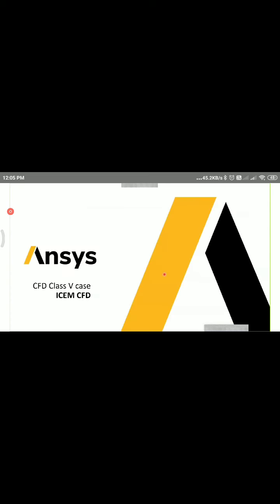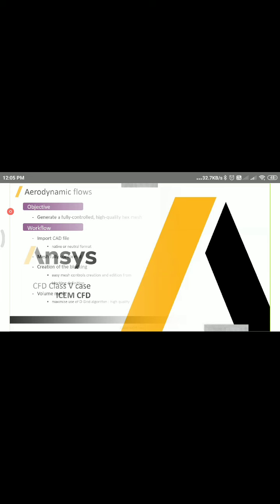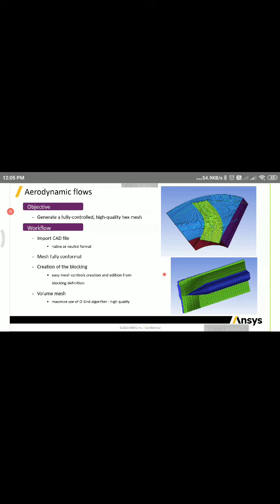And finally, the hexahedral requirement is for ICEM CFD, which is the class 5, where you might have geometries for high-speed aerospace or for any other mixing or reacting flow requirements. You can go with the hexahedral mesh, and in such cases you can use ICEM CFD. You can see this is a CAD, and you'll see small lines there. These lines are nothing but the blocks which are going to take the shape of your geometry to mesh it. At the end, the blocks are going to represent your geometry in terms of a mesh, and that is what communicates with the solver with whatever boundary conditions we have defined.